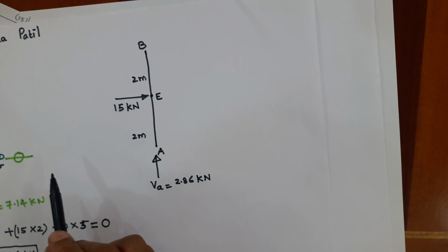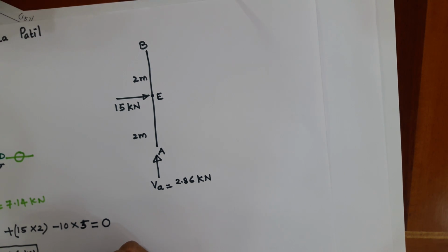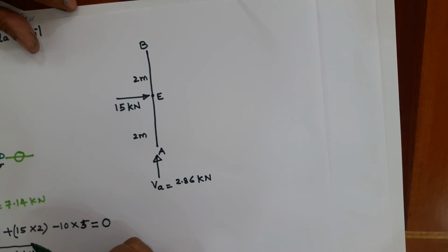So we know the equilibrium rule that for the whole structure to be in equilibrium, each and every point must be under equilibrium. Moreover, each and every element must be under equilibrium. So if I want my frame ABCD to be in equilibrium, that means AB must be under equilibrium. In other words, the three equations of equilibrium must be satisfied for element AB.